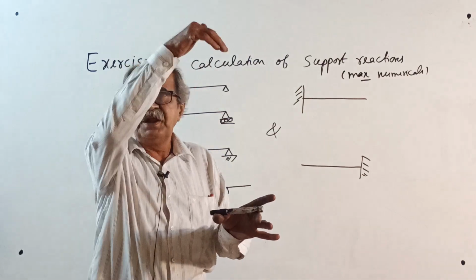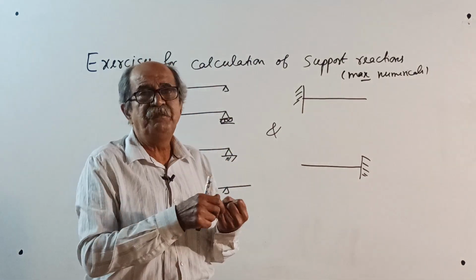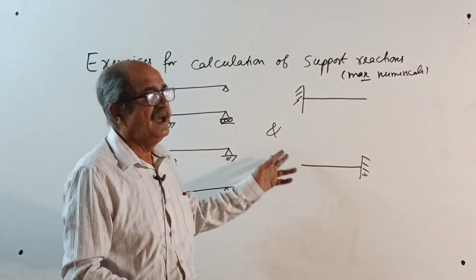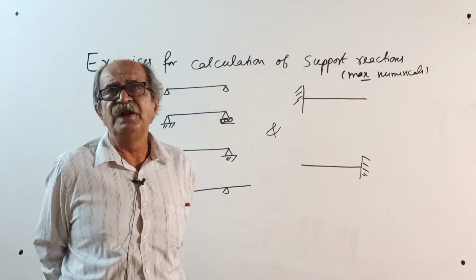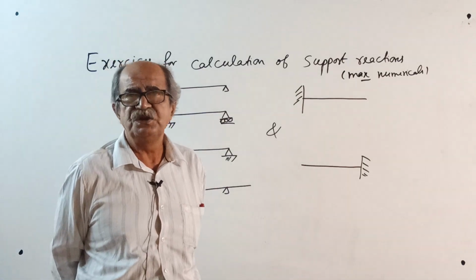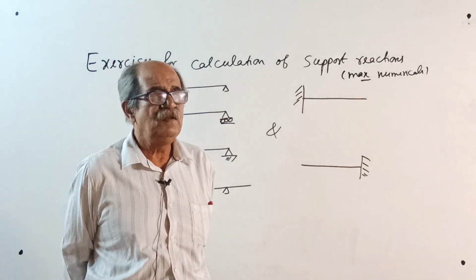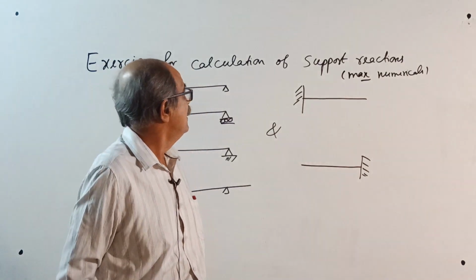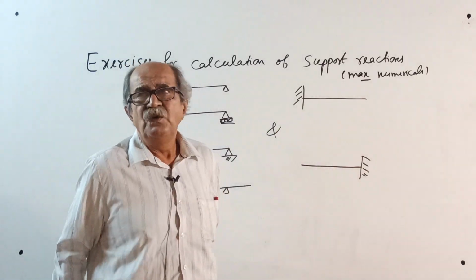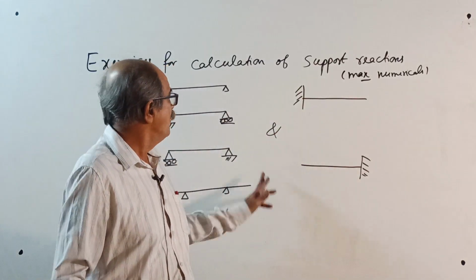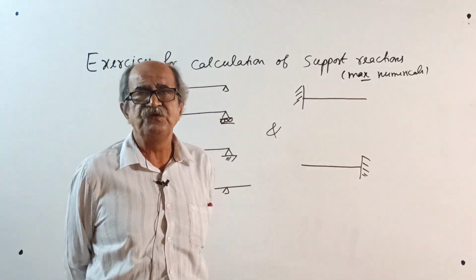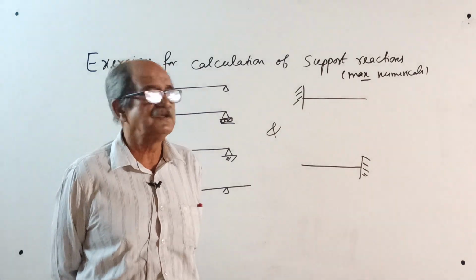Mostly I will give vertical loading, because for SFD, BMD, bending stress chapter, deflection, etc., you require vertical reactions. Horizontal forces have no bending or shearing effect in normal conditions. Actually, secondary effects are there, but we are not considering them. Still, once in a while, in between, I will give a horizontal force also. Then find the horizontal reaction also.